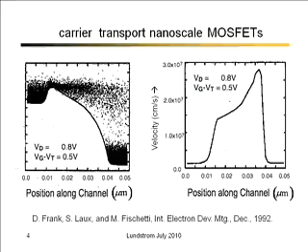Each dot represents an electron that's being tracked through the transistor from the source to the drain by the computer. As it is accelerated by the electric field, it undergoes random scattering processes. So you can see a lot of electrons in the source. You can see them going over a barrier and flowing across the channel. You can see that they're sort of going quasi-ballistically. A few of them scatter and lose energy, but most of them go to the drain without losing a lot of energy. And you can see on the right the average velocity of those electrons versus position.